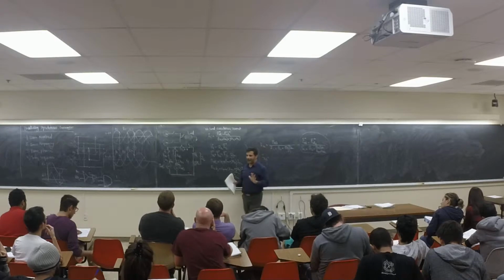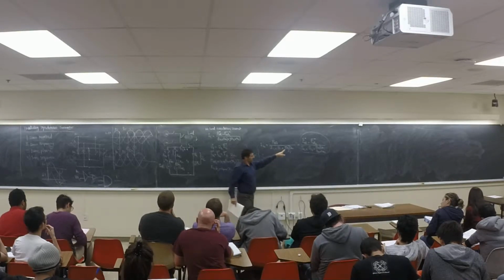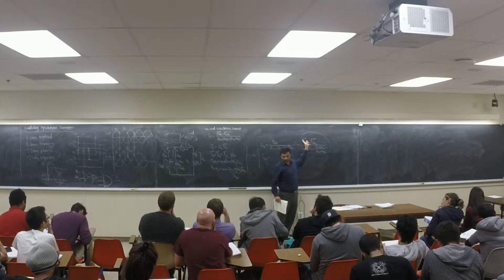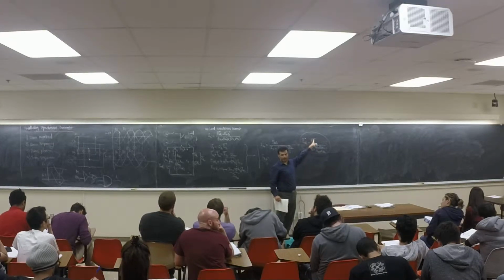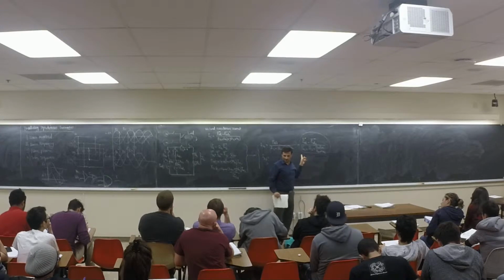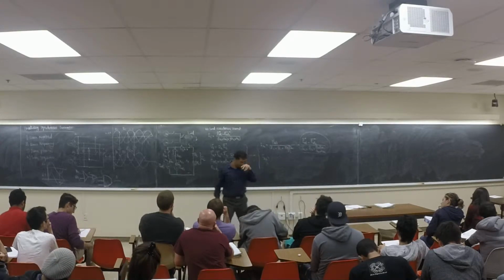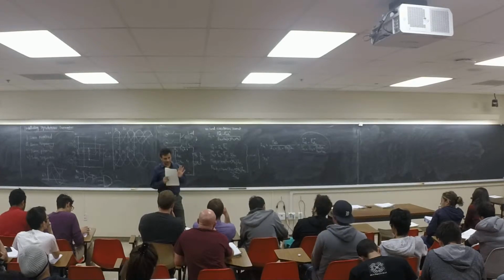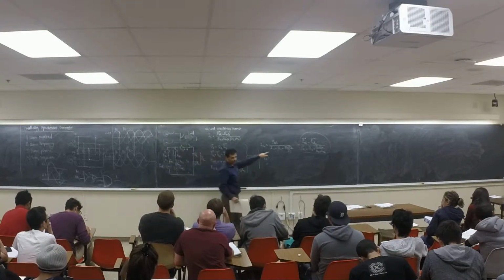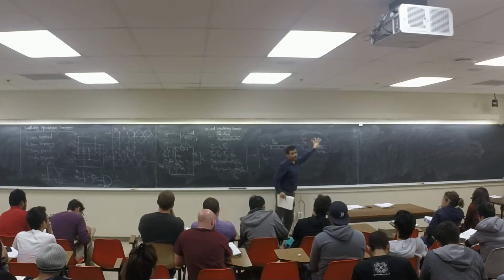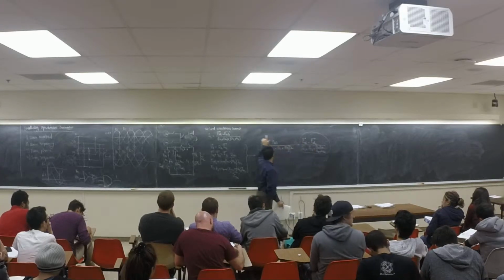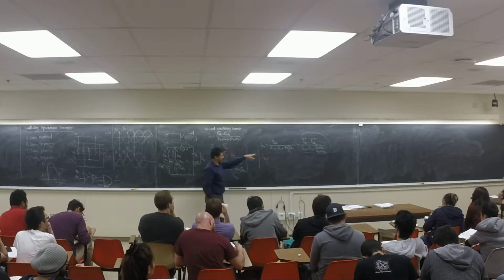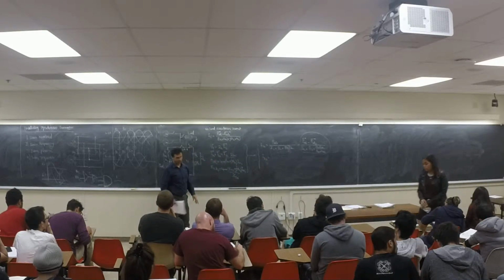If they are perfectly matched, both of them have the same voltage and the same phase, right? If they have exactly the same voltage and the same phase, this one is going to be how much? 0, right? But that doesn't happen, it's very, very difficult to happen. The smaller they are, the better. So this is circulation current under the load condition. Circulation current under no-load condition. I'll figure out that one, and next Thursday I'll tell you what it is.